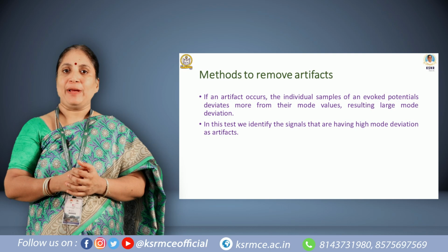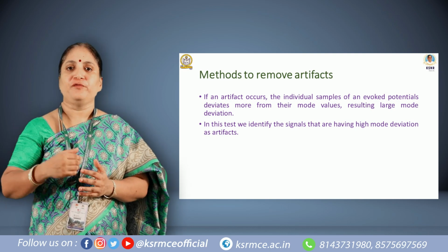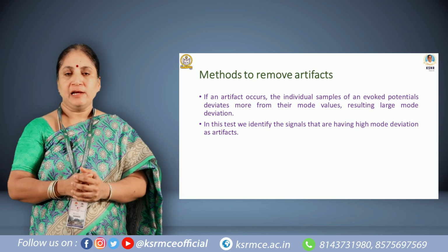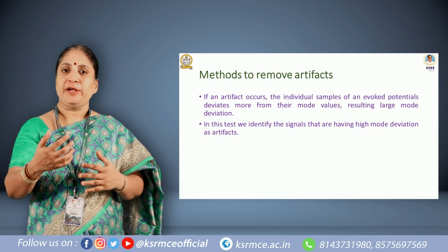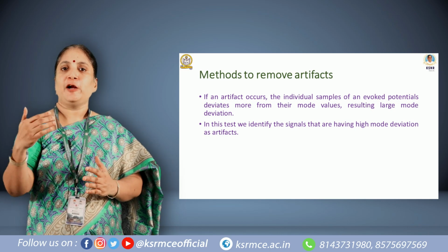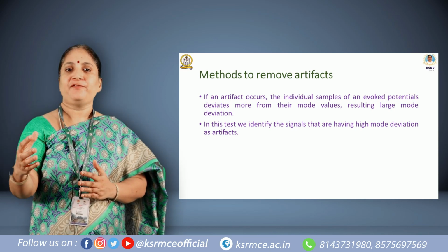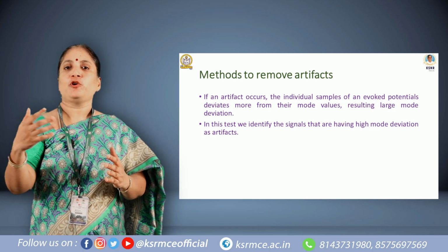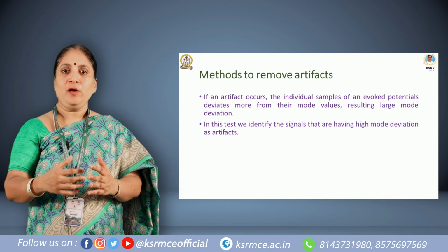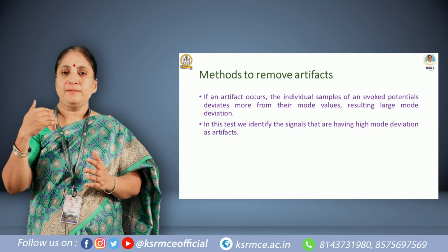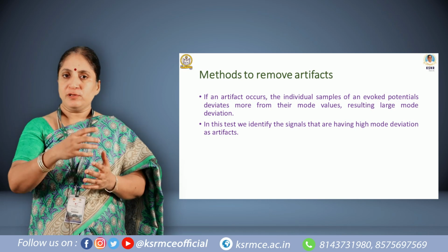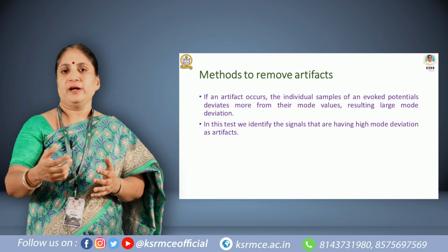If the mode deviation is maximum, that is, it is outside the threshold window. Here also we are going to calculate the mode deviation for all the individual signals, and compare the mode deviations of individual signals with the threshold window. For any signal, if an artifact occurs, then the deviation will be large, so that it comes out of this threshold window. If any mode deviation value comes out of the threshold window, that signal is identified as an artifact, and those channel signals will be removed from the further analysis.